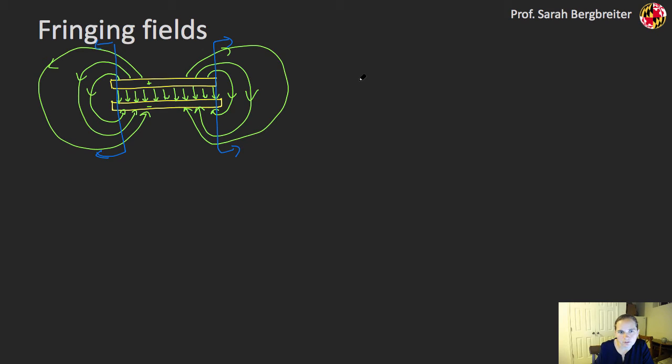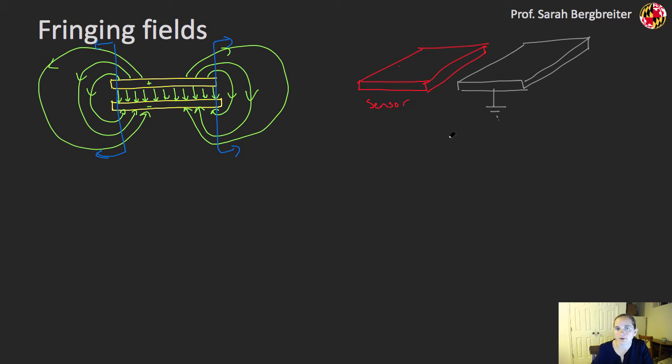In the first picture, I'm going to have a sensor electrode that's flat on a surface. This is something I could design into a printed circuit board, or print on a screen using some kind of transparent conductor. Next to that, I have a grounded electrode. So here's my sensor, and here's my grounded electrode. In this case, the gap between these plates is large in comparison to this dimension, so these fringing fields are going to be pretty dominant, and I cannot model this as a simple parallel plate capacitor.